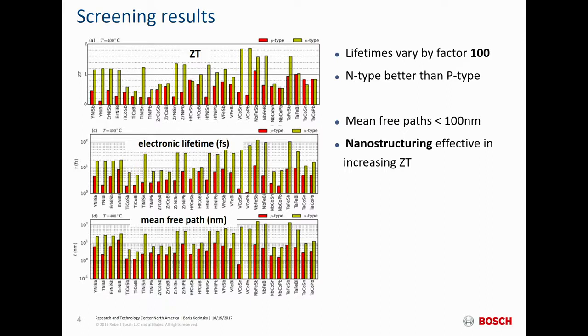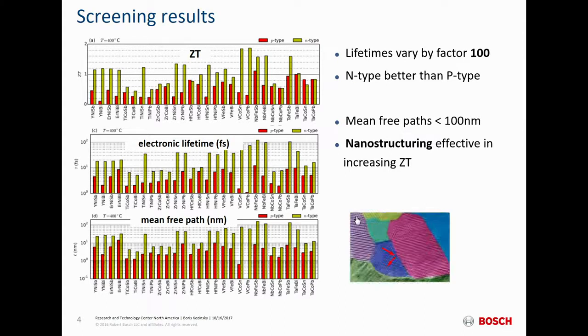What that means in practice is that it's a very good idea to nanostructure these thermoelectric materials. And this is true experimentally, because when you nanostructure, you can't really go to 10 nanometer grains. You usually have grains of a micron, or maybe 100 to a few hundred nanometers. So your scattering of electrons already happens within the grains. The grain boundaries don't add any significant extra contribution there, but they are very effective at scattering phonons, because phonons in these materials happen to be very long propagating modes that are hard to scatter, because of the nature of the material. So these materials benefit quite a bit.